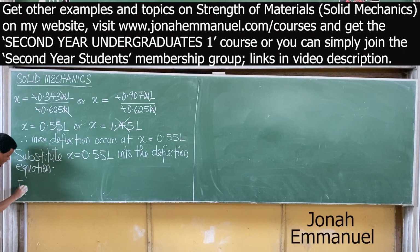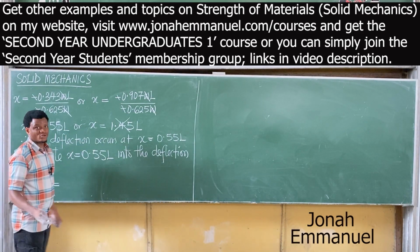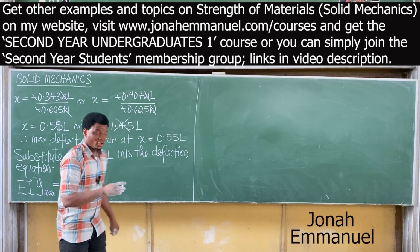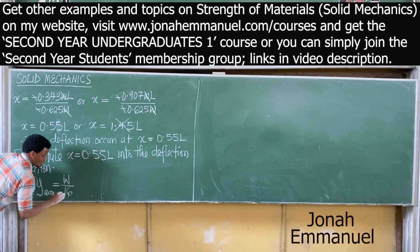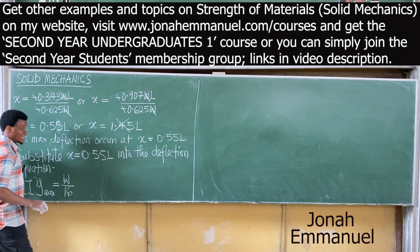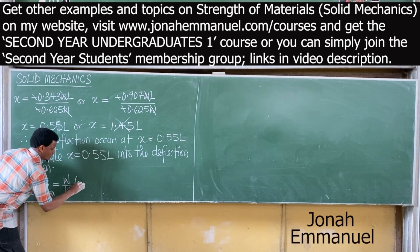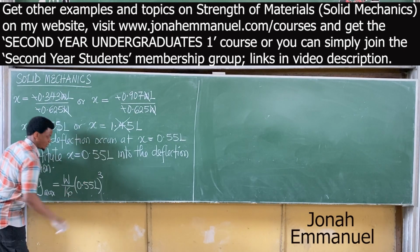EIy, in this case I'll call it EIy max, I'm not looking for maximum. EIy max is equal to, what was the first thing there? W over 16 into x cubed. X is what there? This, so 0.55 L all cubed.